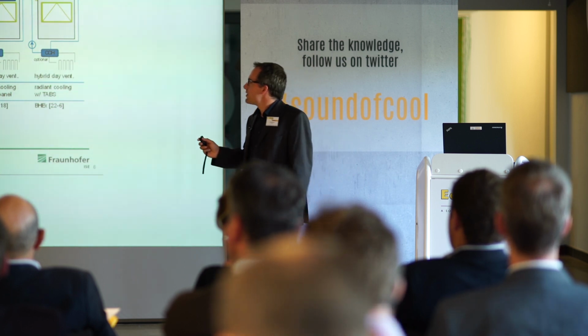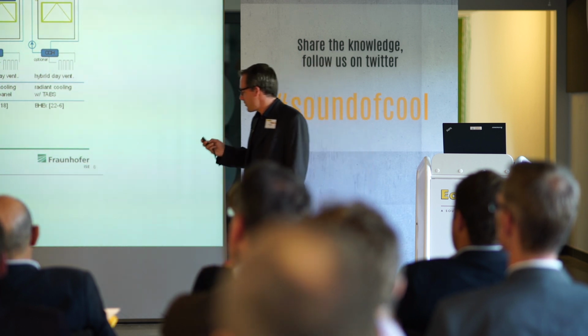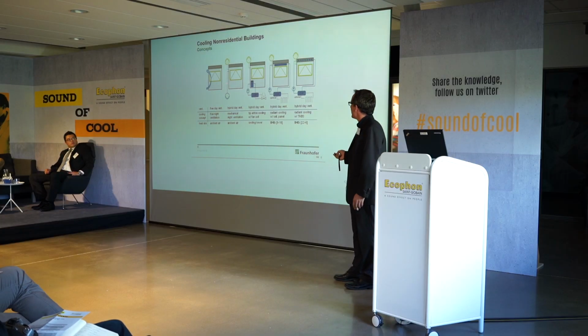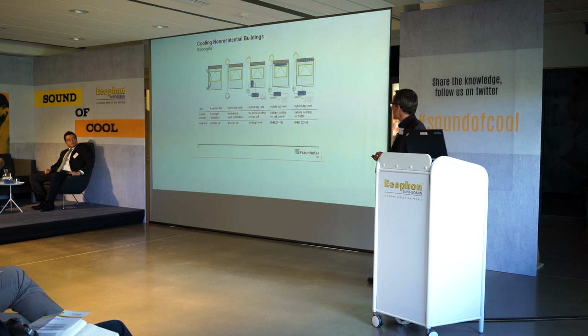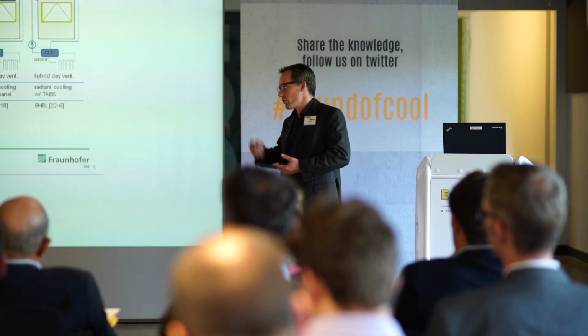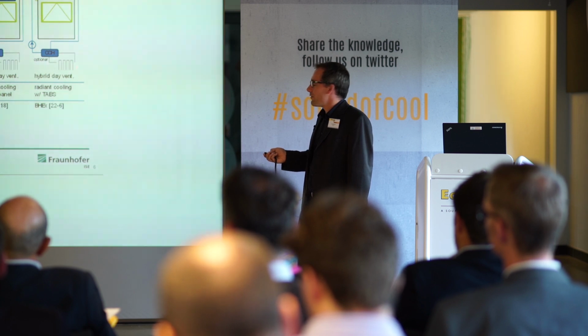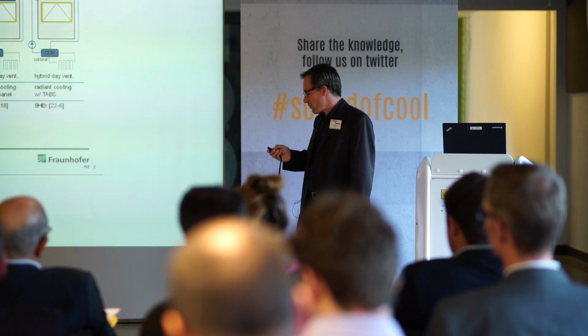So for different cooling systems, we set up a simulation study comparing different concepts, starting with very basic, simple, free ventilated systems, to hybrid or forced mechanical ventilation, to systems with active cooling, for example, fan coils, coming to these TABS systems, where a surface part of the construction is activated and either used or accessing an environmental sink, for example, boreholes, and if needed, an additional compression chiller.